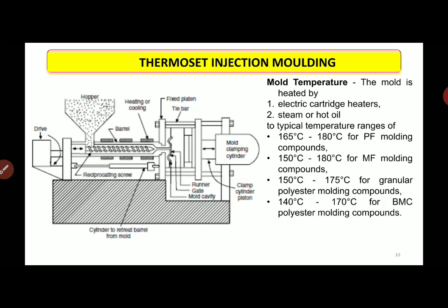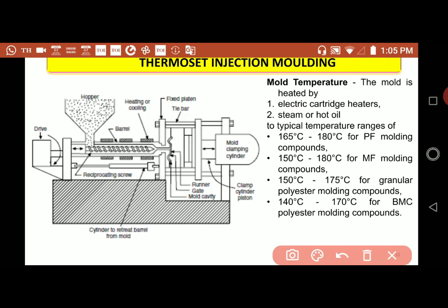Then the mold temperature also affects the process. This is a mold which is heated either by electric cartridge heaters, steam heaters, or hot oil heaters.